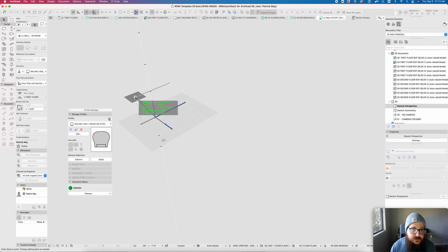Here are the walls. Let's just put these side by side. It's really critical where there are junctions. So I'm going to put that right there, and then we'll see when we isolate these out that for the beam tool versus the wall tool, we get different junction types. The beam gives a nice 45 miter. The wall kind of copes out, and this adds actually a deceptively high number of polygons and complexity to the model processing.